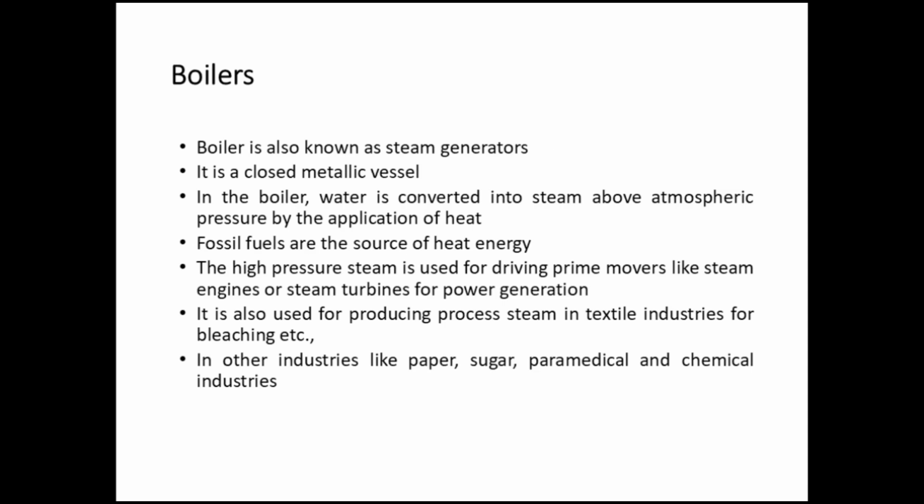Boilers. A boiler is also known as a steam generator. It is a closed metallic vessel. In the boiler, water is converted into steam above atmospheric pressure by the application of heat. Fossil fuels are the source of heat energy. The higher pressure steam is used for driving prime movers like steam engines or steam turbines for power generation.